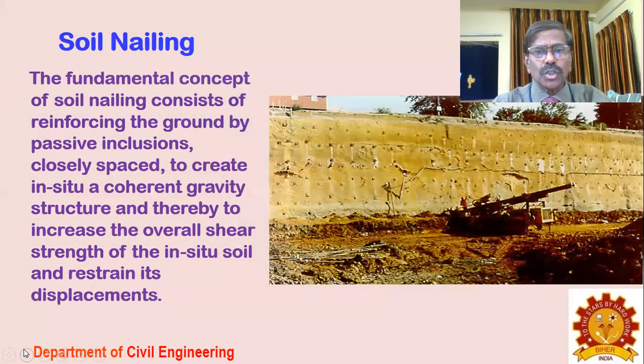Sometimes there is nailing of the soil. You take some solid block or a steel block or a timber block. You have a hole in that, and through the hole you embed a steel rod. Then you pull the steel rod and jack it up and lock it with a lock nut. Then that amount of post tension applied on the bulkhead will apply a pressure on the soil to retain the soil. You call it soil nailing.